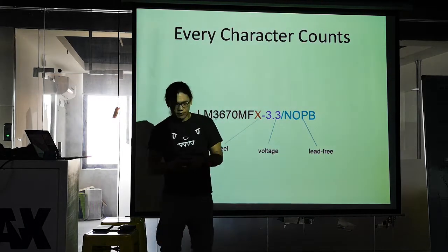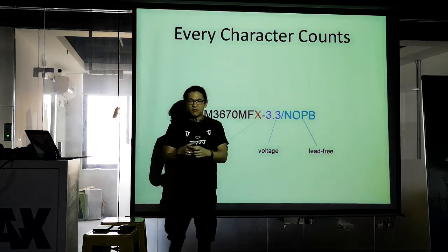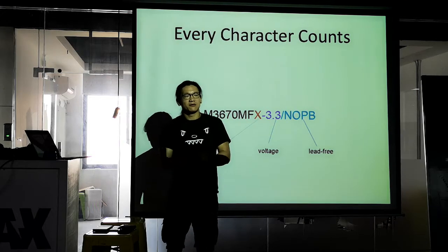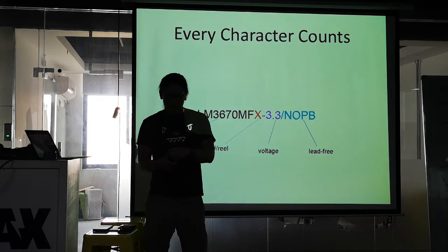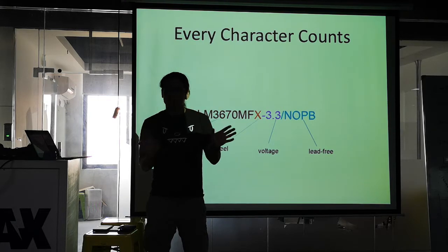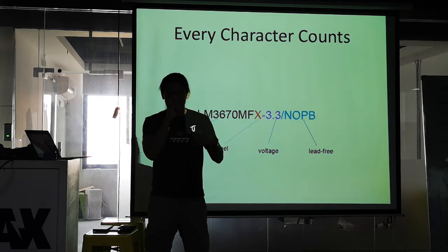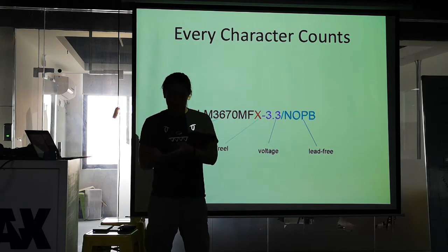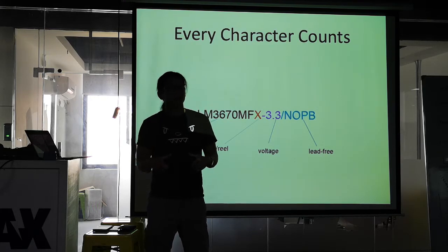If you work with a Chinese factory and you don't specify this reel number or use a default, they will buy the amount that you specify, right? Because the part number for 3,000 on a reel had fewer characters, it seemed like, for whatever reason, it was at the top of the list when you were entering your Altium schematics. That factory will quote based on you wanting to buy 3,000 of these, right?